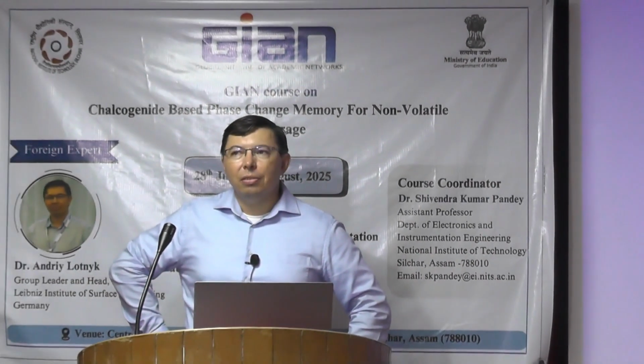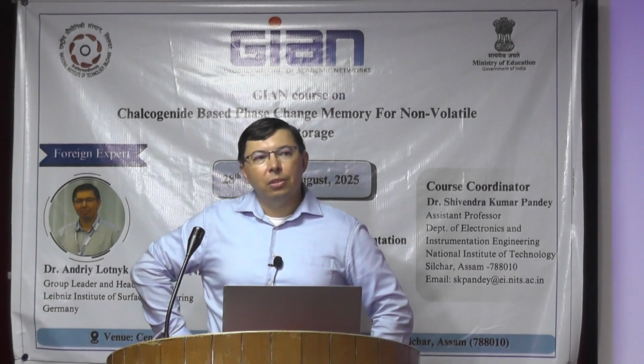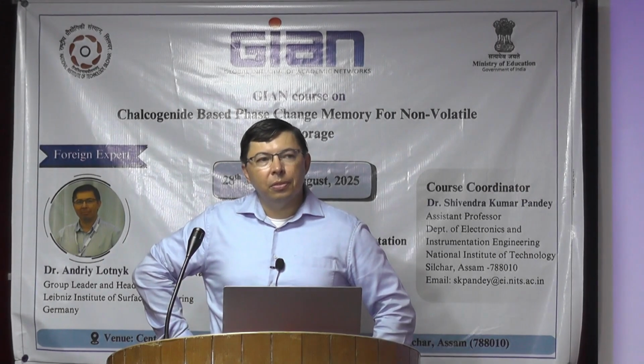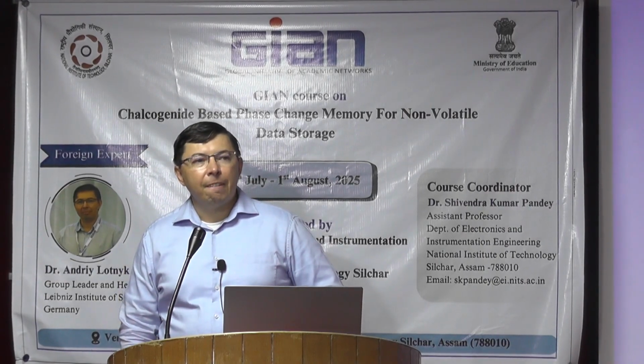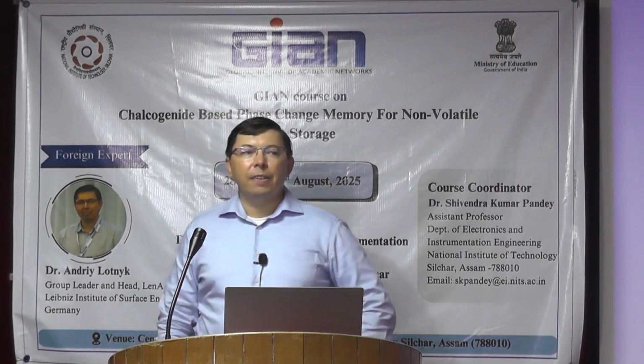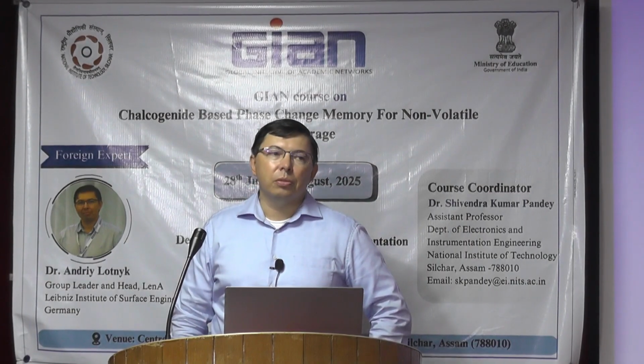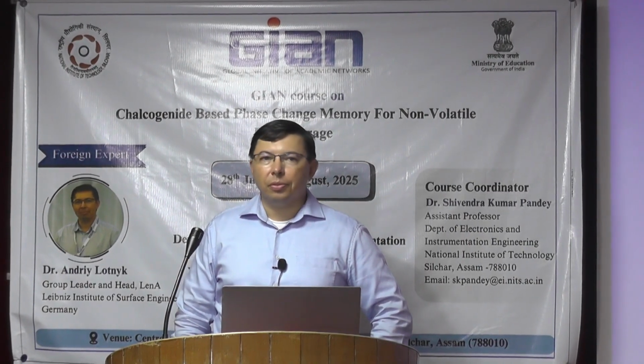Okay, so after deposition you just cap with material in the same vacuum. So the desiccator way which you are telling, definitely it will affect. For the time being you are taking the sample from your system and keeping it, so in between there is enough time to get oxides. So in the chamber itself, if you just cap, there are some capping materials, and later there are some liquid processes, you can take it out and then characterize.